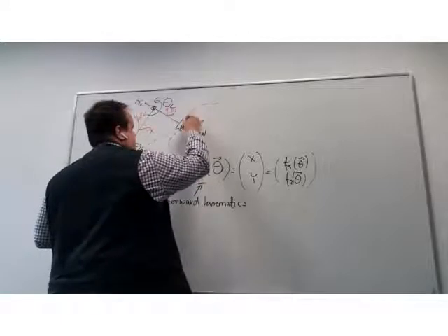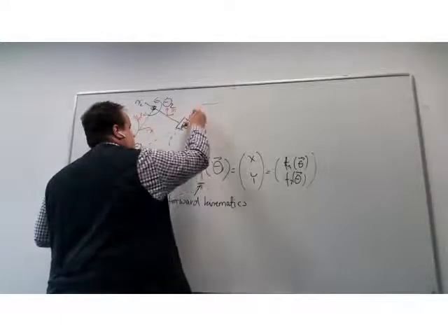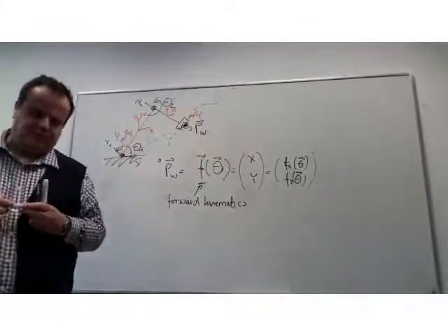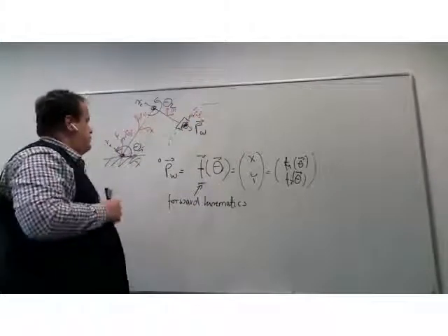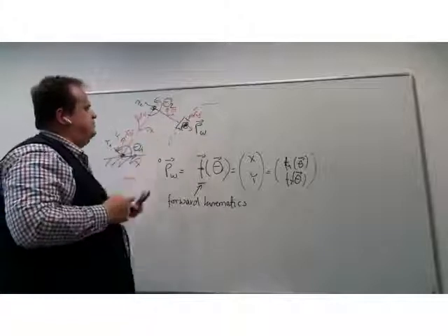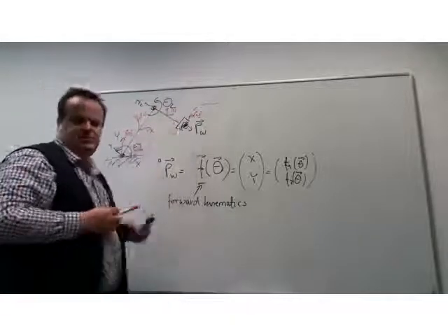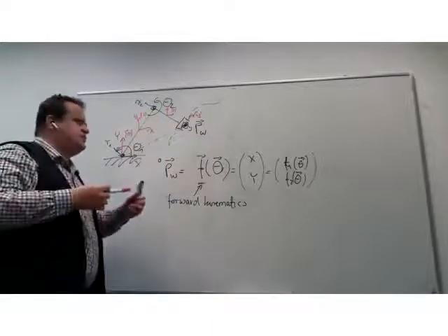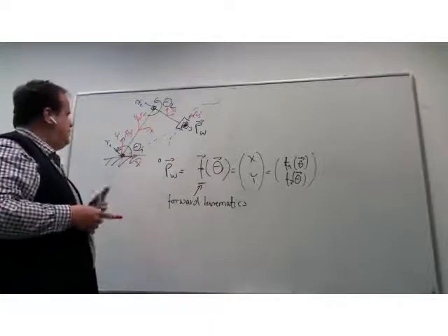And usually for convenience, we will also attach the coordinate frame of the wrist to the last link. I'm saying for convenience just because there is usually a rigid connection between the last two. It's just to simplify the calculation.